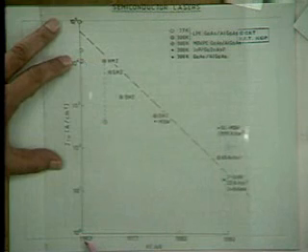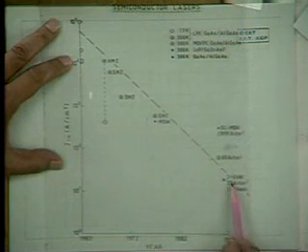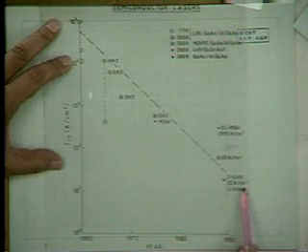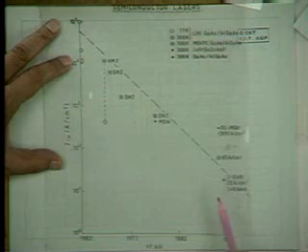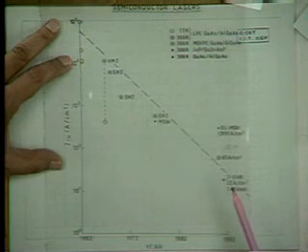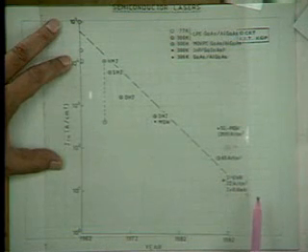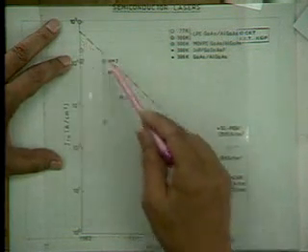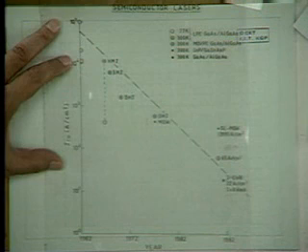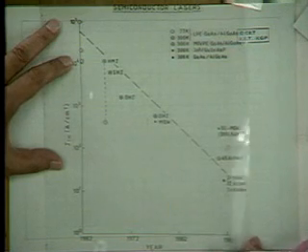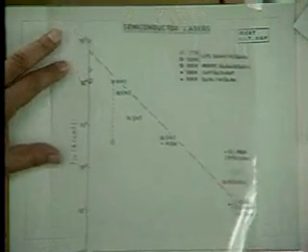And in the last 30 years, now we have lasers in which the threshold current density has come down to about 20 amperes per centimeter squared. This is using novel techniques like multi-quantum well devices grown by molecular beam epitaxy. And so the tremendous improvements in semiconductor lasers in speed and power output and efficiency has spurred this optoelectronic revolution of the last